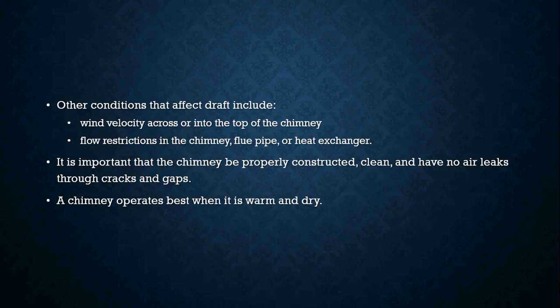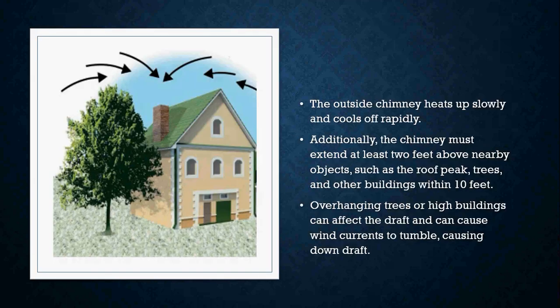Other conditions that are going to affect your draft are wind velocity across or into the top of your chimney, and flow restrictions in the chimney, flue pipe, or heat exchanger. Those are also going to affect the way this guy drafts and removes those flue gases. It is important that the chimney be properly constructed, clean, and have no air leaks through cracks and gaps. A chimney operates best when it is warm and dry. The outside chimney heats up slowly and then cools rapidly, right? It's because it's going to be exposed to the outside air.